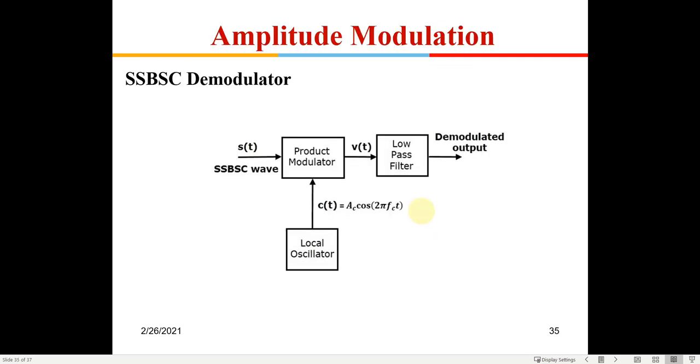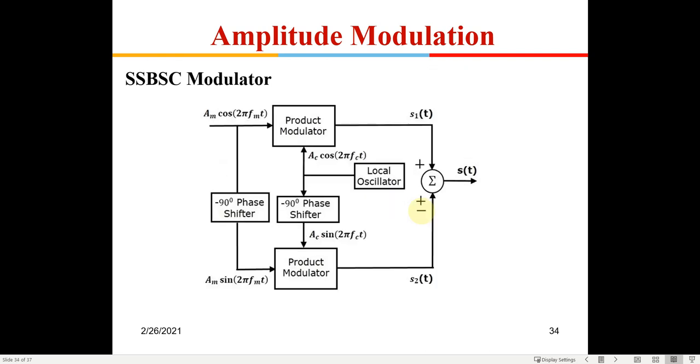Otherwise it would be pretty clear. You can do that yourself. You can just multiply these two equations, and you can multiply these two equations, so you will get S1 and you will get S2. And at any given time, like I said, you don't get carried away by this plus minus sign. Why is it given plus minus? You can either transmit the lower sideband or the upper sideband. So if you do addition, you will send the upper sideband. If you do the subtraction here, you will send the lower sideband. So this is the single sideband modulator which we use.